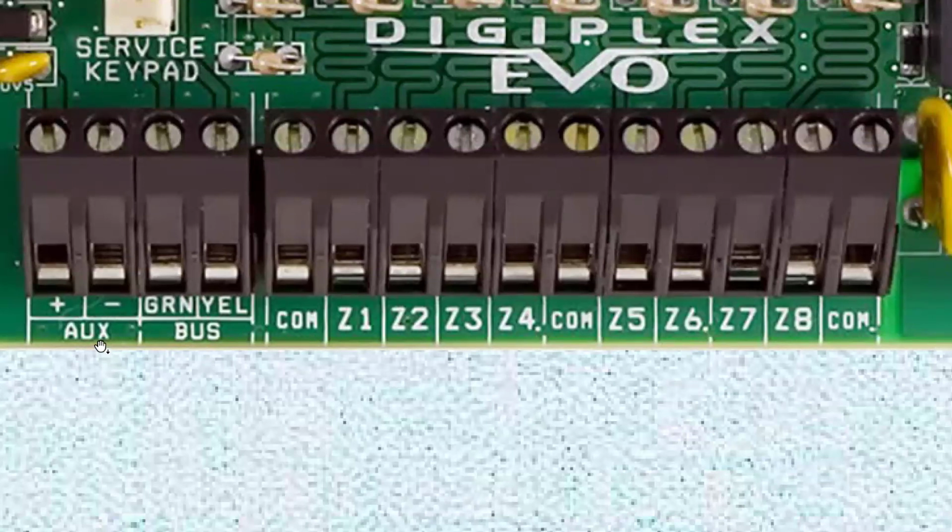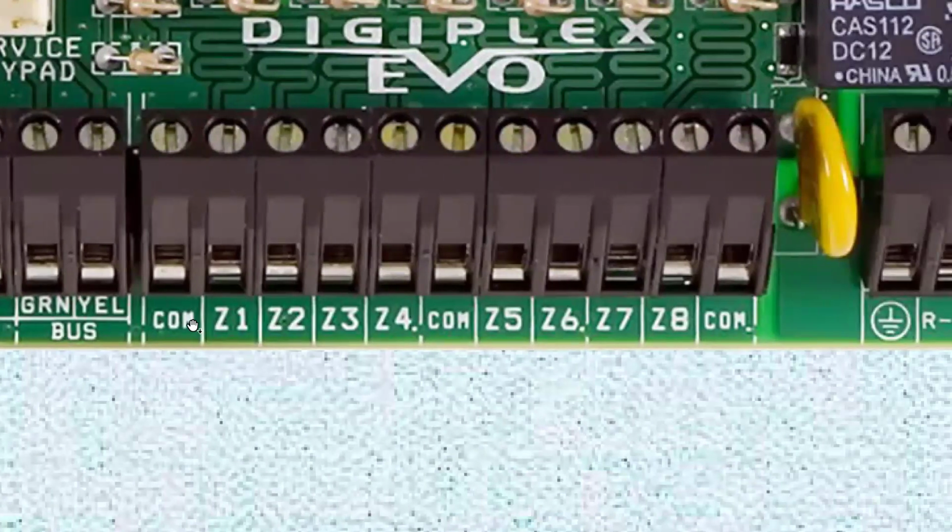And since they are common devices, power is going to be just distributed parallelly to all of them. It is going to be the bus, because it's a bus configuration. So you're going to connect green and yellow to the first keypad, and then a parallel connection, just tap off of that and continue. Next keypad, tap off parallelly, and the next one, because it's a bus system, so everything taps into that pair, green and yellow. Right? Next, we go here.